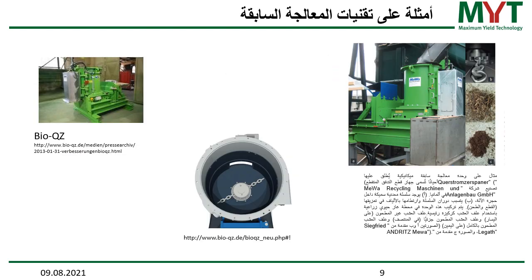The next one is this cross-flow shredder. As you can see, it's a very simple system, as you can see in the picture in the middle of the slide here. It's actually only a chain which is rotating at a very high speed at the bottom of this unit, and by forcing this chain through the substrate, it destroys whatever comes into this vessel.